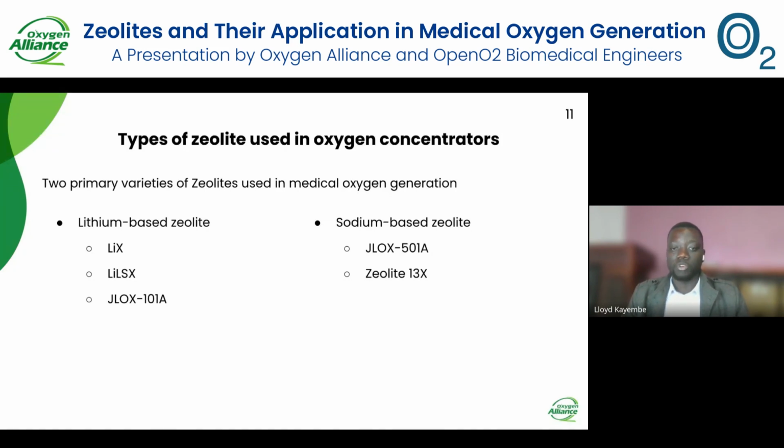Because of the presence of these ions, they affect the properties of the zeolite. Sodium ions are larger than lithium ions, and this slightly affects the size of the channels and pores within the structure, which potentially affects the adsorption properties. Lithium-based zeolite outperforms sodium-based zeolite in terms of efficiency in the adsorption of nitrogen.